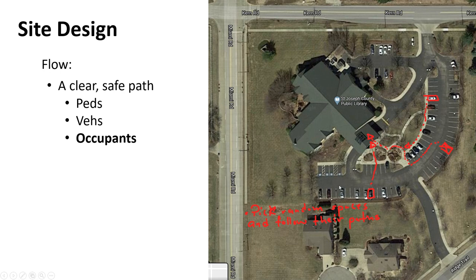On a parking lot with drainage design, you drop the water balloon. Where is that water running? You do that in your head all the time when you're designing these, to make sure that you don't have a flat spot somewhere you've missed. All right, we put elevation points at these corners usually of the parking areas, and then we don't put much else out in the middle, but internally you've got to think about, well, is it really graded all the way across there? Is it straight graded? Do I need to add in a low spot and a drain? We do the same thing with cars.